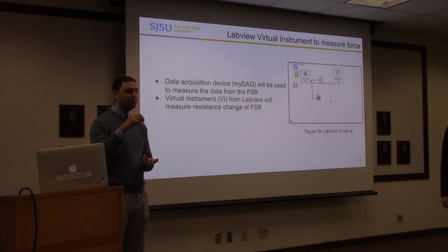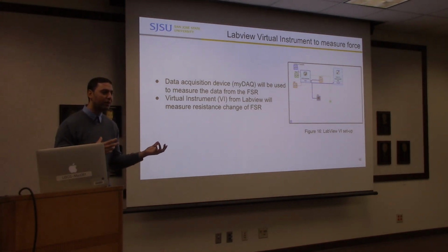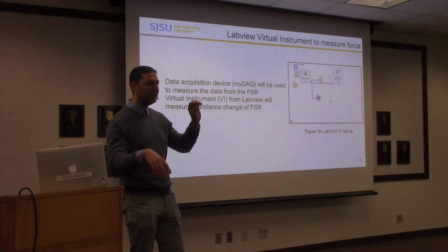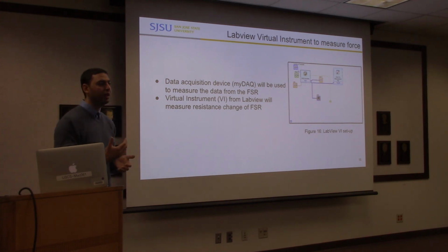So we will first calibrate it with known load and correlate what we'll be reading with a known load. So for example, we apply 1 Newton and see what that is on the LabVIEW. So from there, we'll know what load we are applying.